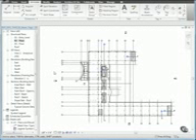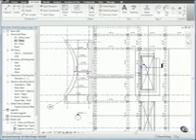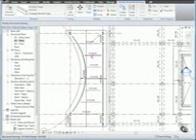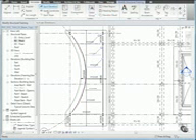When you do, a beam tag is added to the top middle location on all beams within the plan view. Let's add an end reaction value to the steel beams of the entryway. Using the Control key, select multiple beams located in the steel frame of the entryway. Then click the Annotate tab, and from the Tag panel, click Beam Annotations.